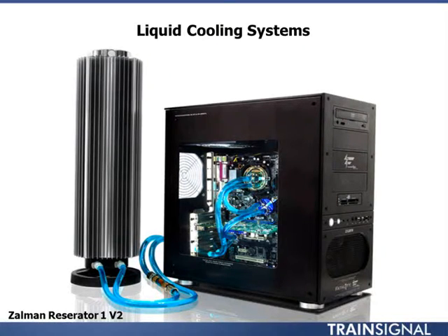You're usually going to use liquid cooled systems with gaming systems because they generate so much heat. Pretty much, the cool liquid runs through a chamber connected to the CPU, the cool liquid absorbs the heat, and then the heated liquid returns to be recooled. There's oftentimes some sort of refrigeration system working with this as well.